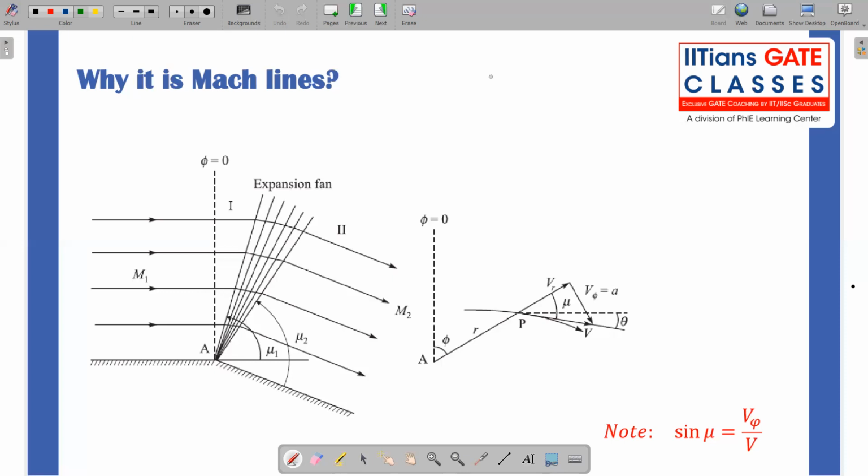So when the flow is moving in a diverging section like this, we see a supersonic flow will accelerate further in the diverging section. It's a contrast to our low speed counterpart, where we have seen that if Mach number is less than 1, in the diffuser, the flow decelerates. We call it a diffuser because the flow is decelerating. But when it comes to a supersonic flow, whenever the flow sees the diverging section, the flow will accelerate.